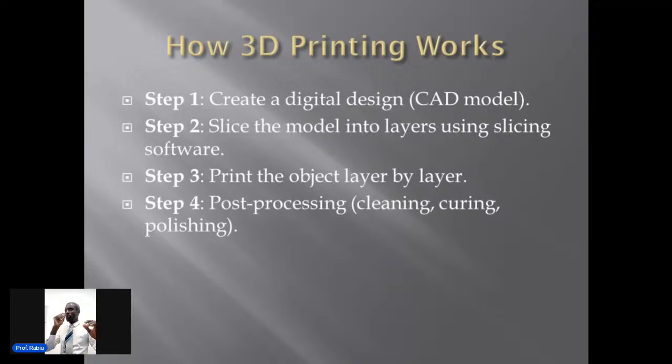Just imagine you have to print teeth for dentists. They do polishing. When they print, they have to do some polishing to make sure that it looks nice and smooth. If you look here, it's layer by layer. Still, it's showing the rough, right? Though it's smooth, it's rough. You can feel it. So if you want it to be smooth, you have to come and do the polishing, sometimes waxing and all that, depending on the type of the material. Is that clear? Do you have any question?